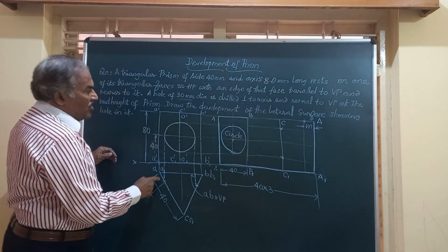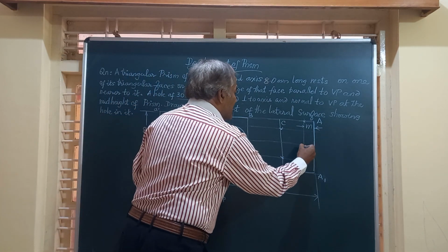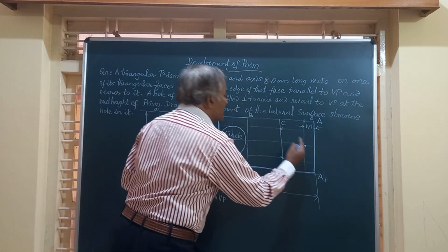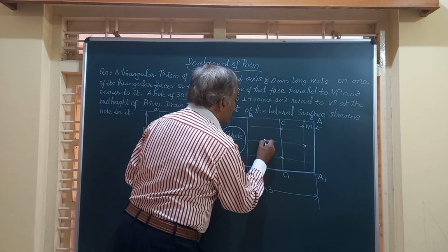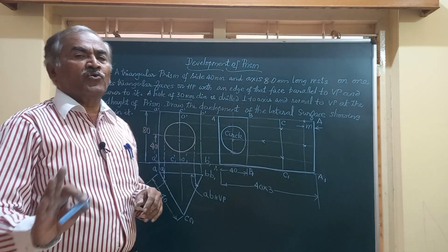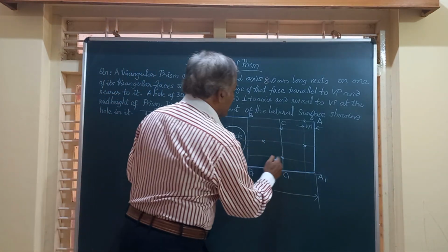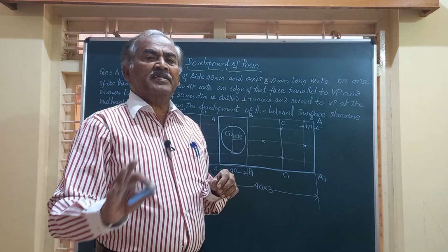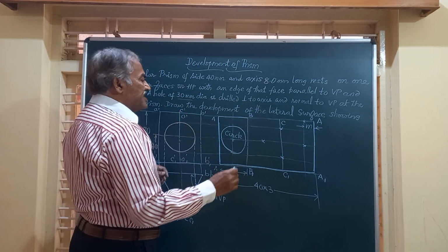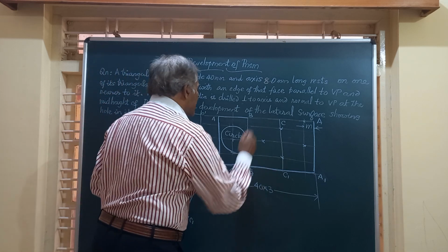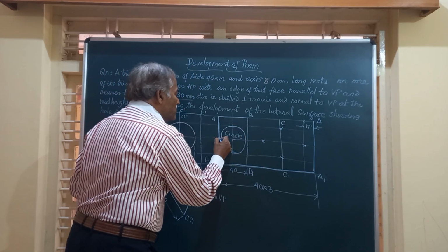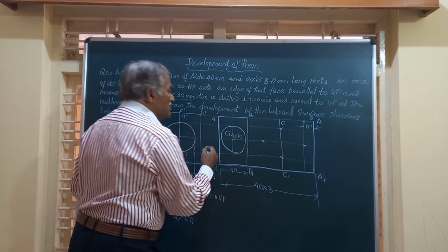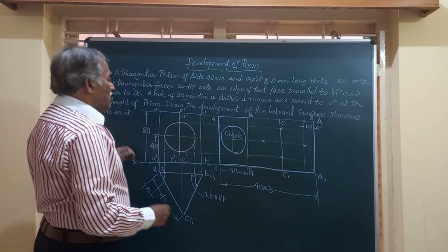So friends, on this line, you get a point here where it is meeting the center line. Similarly, at equal distance on the other end, also you get another point. So there are 4 points to draw the ellipse here, but minimum 8 points are required to complete the ellipse manually. So let us draw 2 more. So 4 more points you will get. See, you had 1, 2, 3 and 4. And now we will have four more points. How to get it?